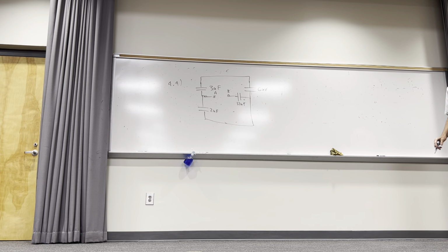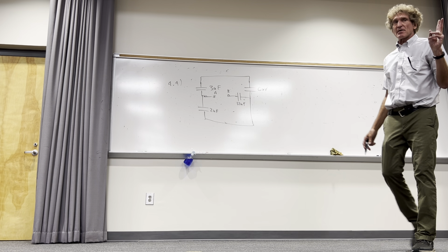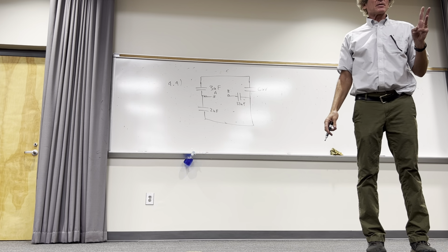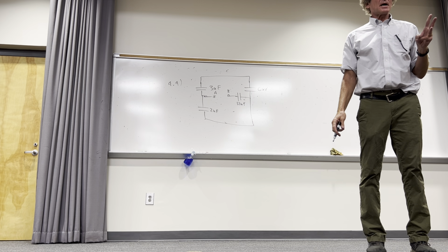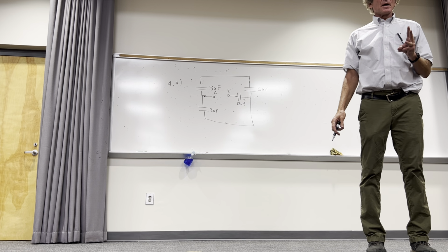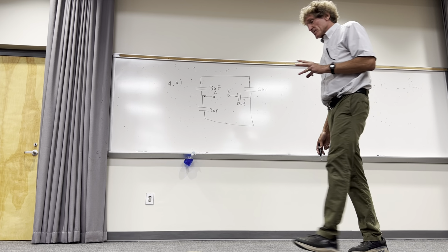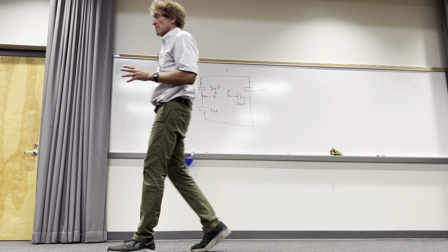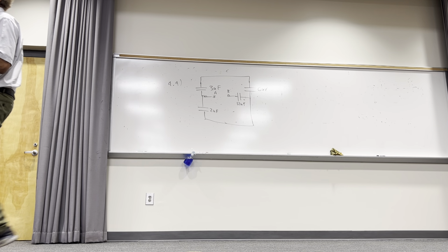Now, think first, identify what's in series, and then in parallel, and reduce the complexity. Hear me, class? Take a moment, and remember what I said. Capacitors in series add like resistors in parallel. Capacitors in parallel add like resistors in series. I showed you the actual mathematics a second ago. You all with me, class? Did they do this in physics, by the way? Okay, good. This should be something you see.